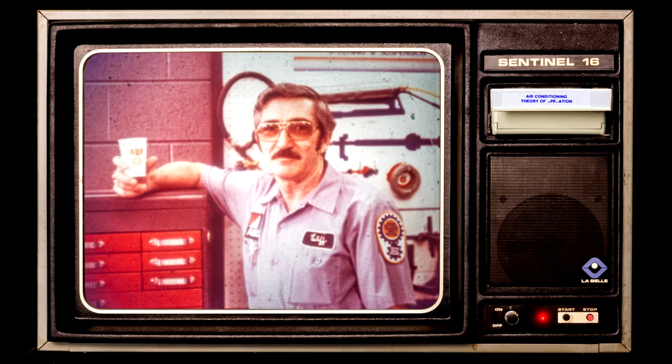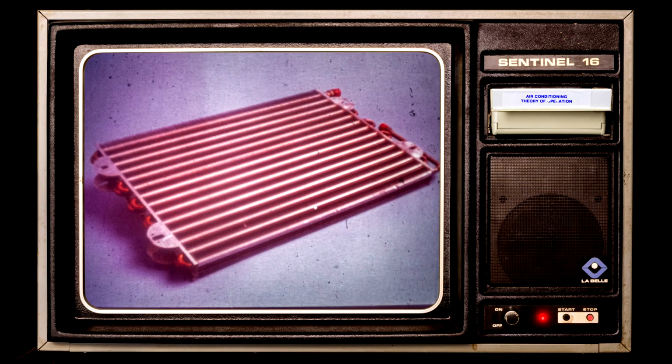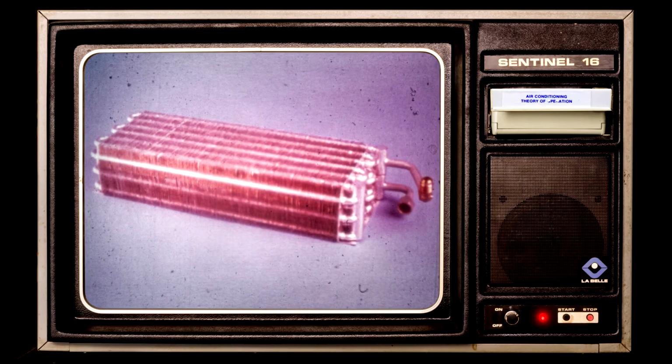Now let's put together an air conditioning system piece by piece. We'll use automotive components, but remember the same theory applies to building air conditioning systems. As we go along, you'll see how the principles we discussed relate to the behavior of R12. First, we need a condenser, which will allow the heat from the interior of the car to be given off to the atmosphere. And we'll need an evaporator, where the interior heat is absorbed by our system.